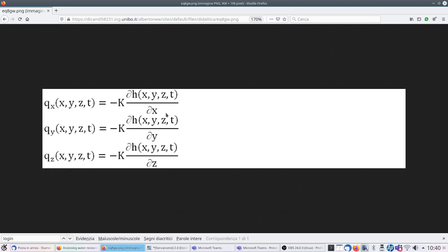So when we talk about a vector, you cannot talk about conservation of energy because energy is a scalar. We have to talk about conservation of momentum, but they are strictly related. When you have an equation which relates flow, which means a kind of change in energy, because flow can only occur if you fuel the flow with some energy. So when you write an equation relating flow to a change in head, as you can see here, this basically relates flow to a change in energy because head is energy. So it's an energy equation.